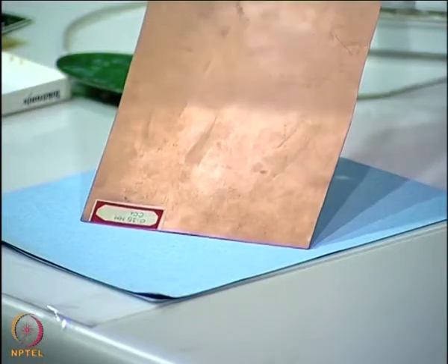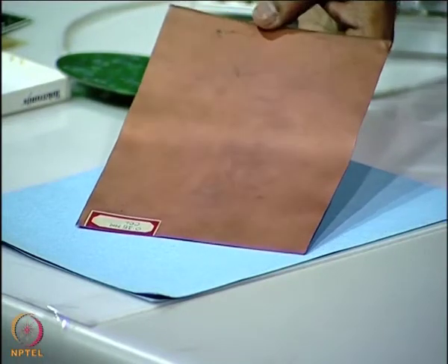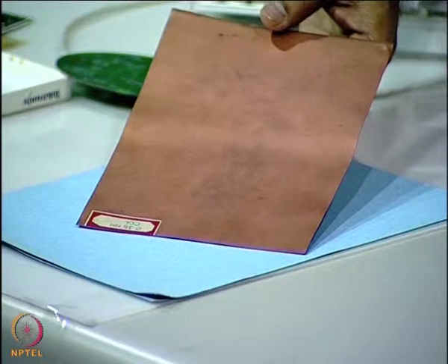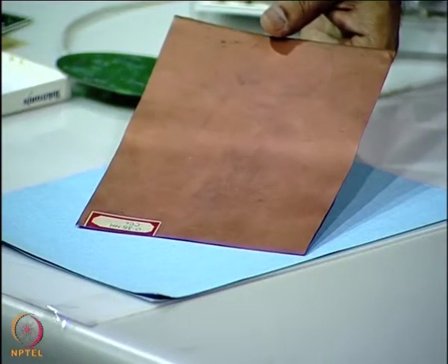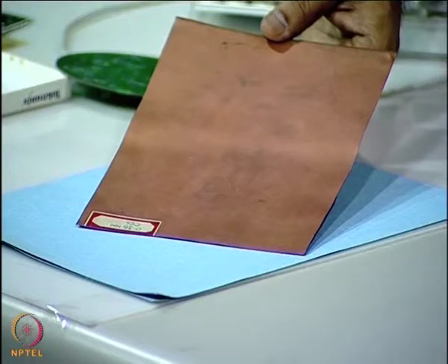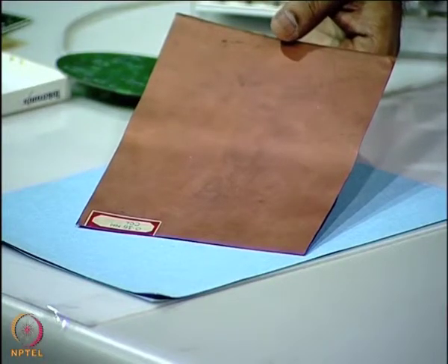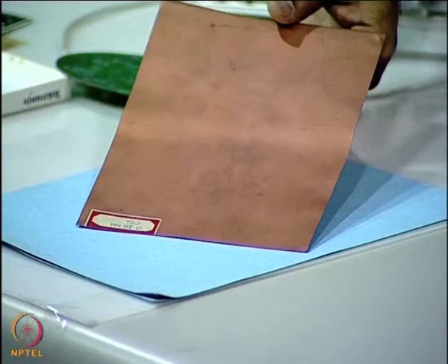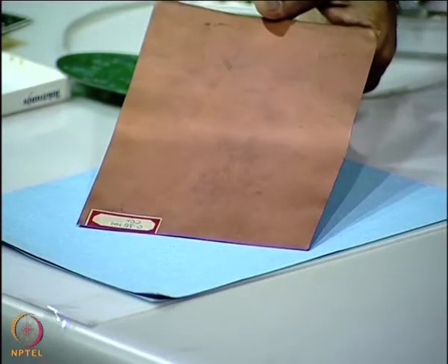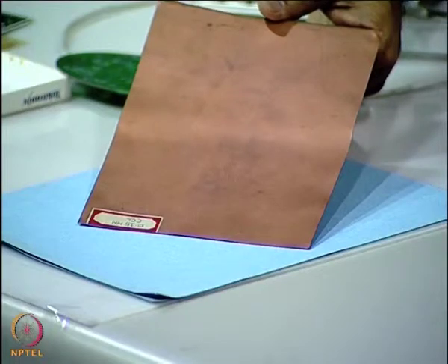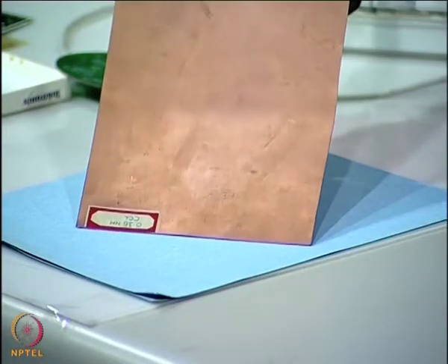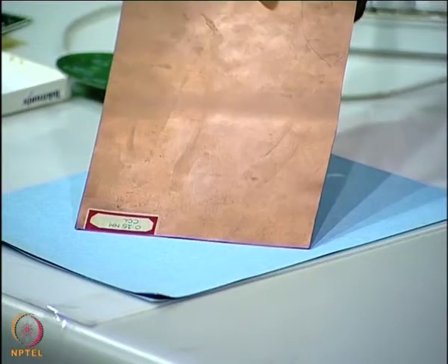This comes in various thicknesses, right from 0.5 mm to 3.2 mm. The thickness of copper and the dielectric can vary accordingly and according to the required thickness. This can be used as a system level printed wiring board substrate, and it also can be used as an inner layer substrate in the manufacture of multi-layer printed wiring boards.